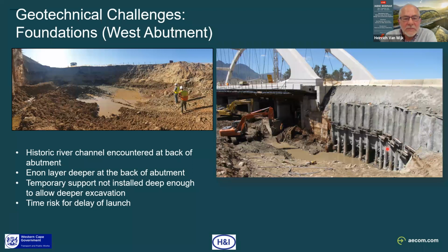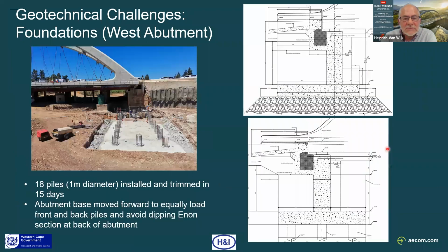So over the December period, we managed to get piling contractors onto site, and we converted that abutment to a piled foundation, and also modified the footprint slightly to balance our pile loads, and obviously all the settlement and loading constraints were taken into consideration.